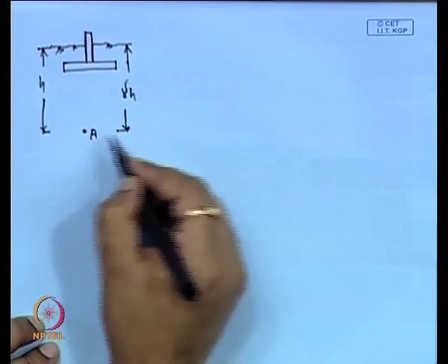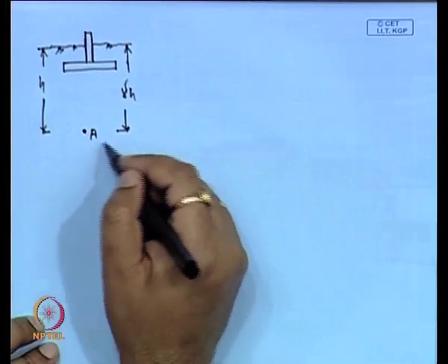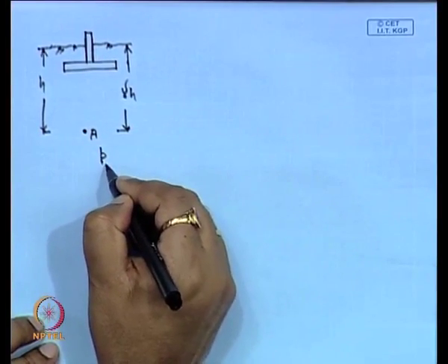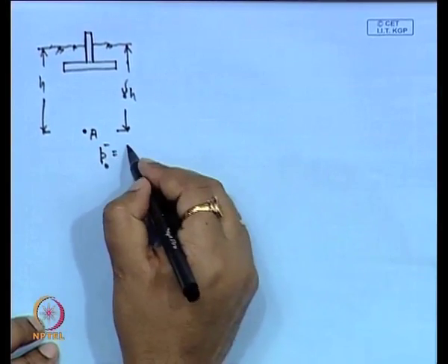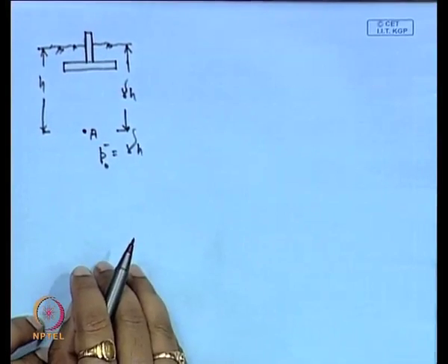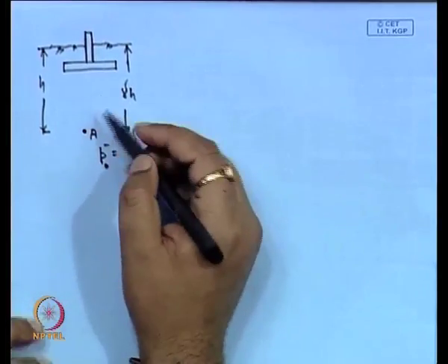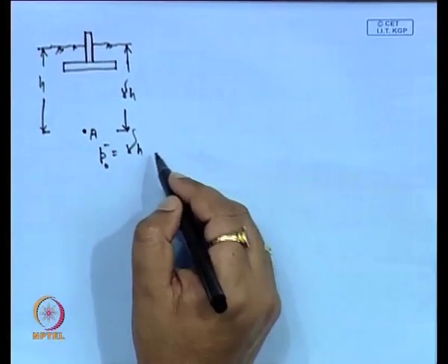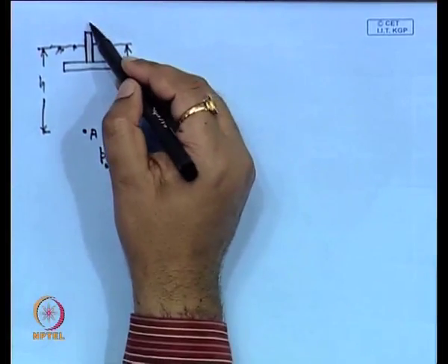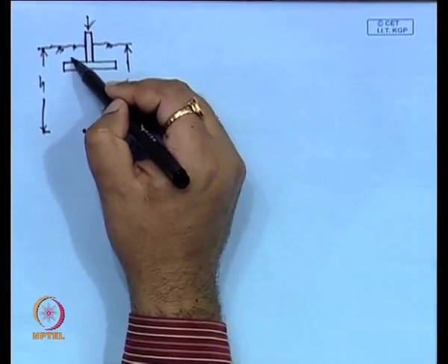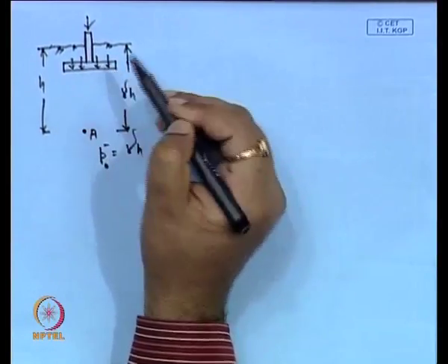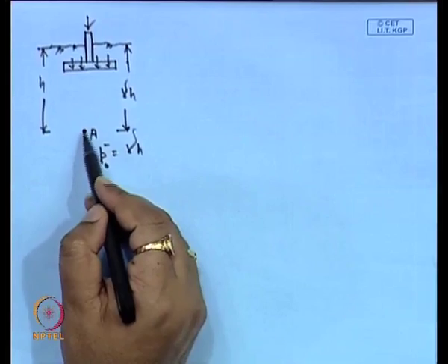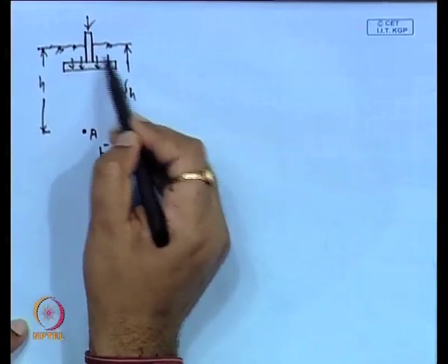So, this is the stress at point A before the application of the load, or the effective overburden pressure at point A before the application of the load. We are not considering the water table effect here. Once we apply the load through the footing, additional load will act at point A due to the foundation load.